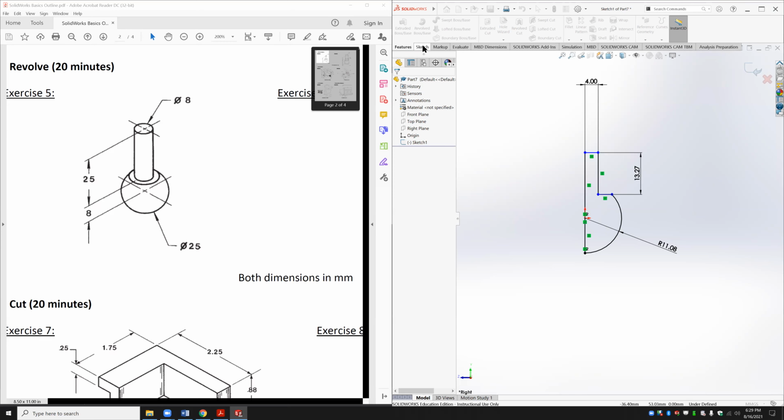So when I did the circle, and then I made sure that there's relations, and then I press the trim, it just showed the circle, but it doesn't trim. Oh, you may have the same issue that I had originally. If you zoom in to the intersection where you're trying to trim, do the lines overcross with each other? Do they intersect? They do. Okay, that's strange. I actually made sure that there's relation. So I can see the relation.